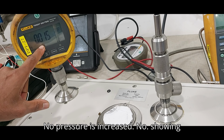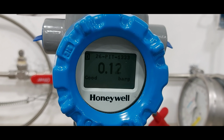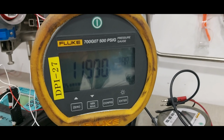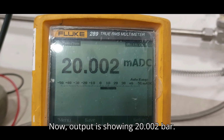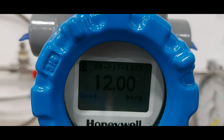Now pressure is increasing. Once you reach 12 bar, now pressure has almost reached 12 bar. Now output is showing 20.002 milliamps. The display shows 12 bar.